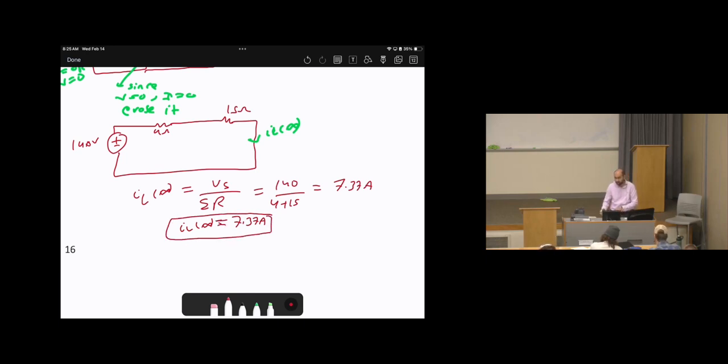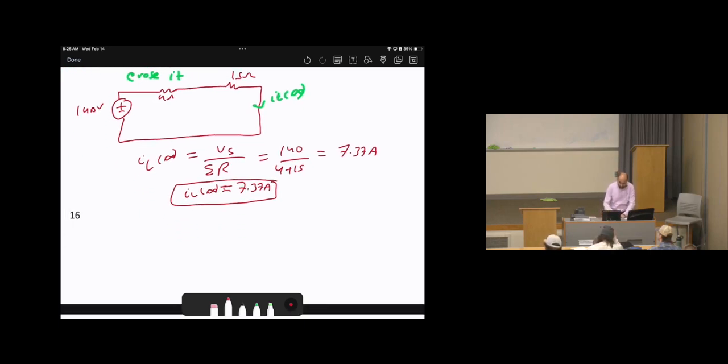Yes, we are done, but we still have some more steps to do. So basically, if there are 25 points for this problem, now I'm done with 15 points. I still have 10 points left. Okay, where do these 10 points go? The first thing is to substitute this in the formula to calculate, for the next 5 points, IL of t equals IL of infinity minus, IL of infinity minus IL of 0, e power negative t over tau.